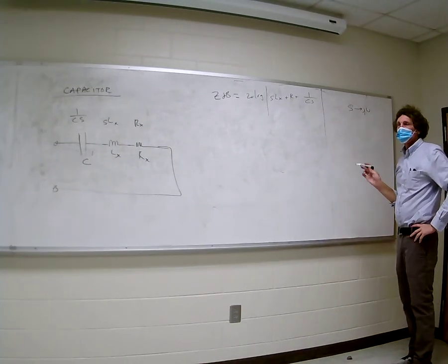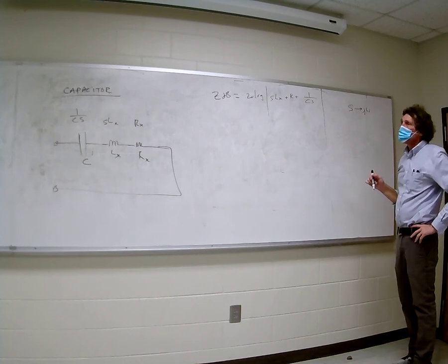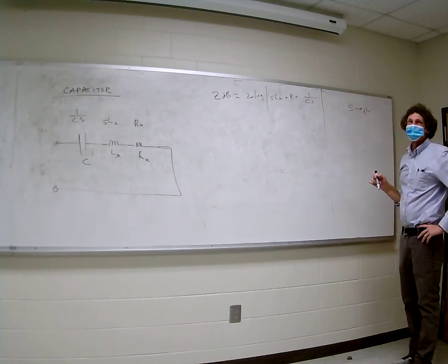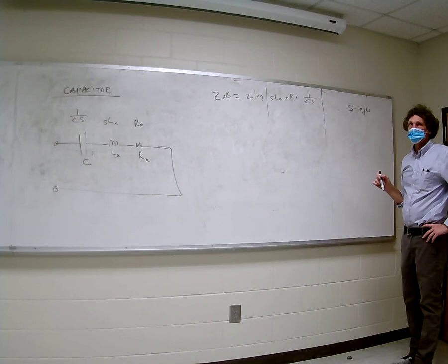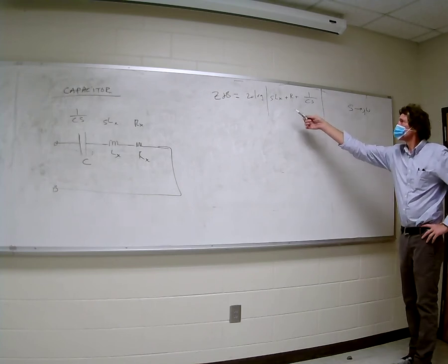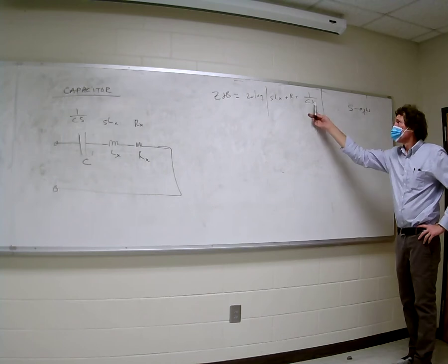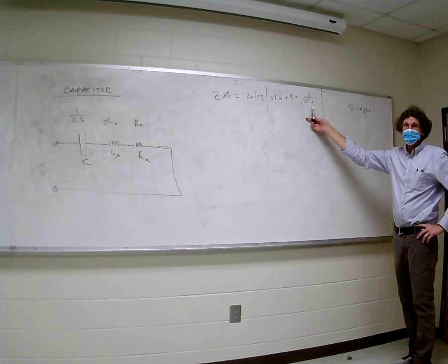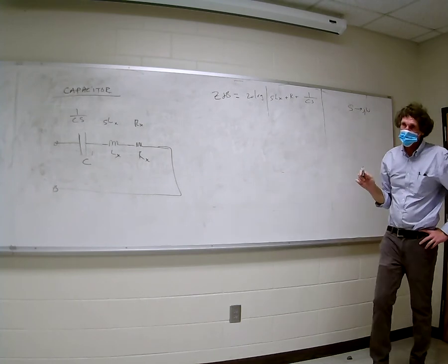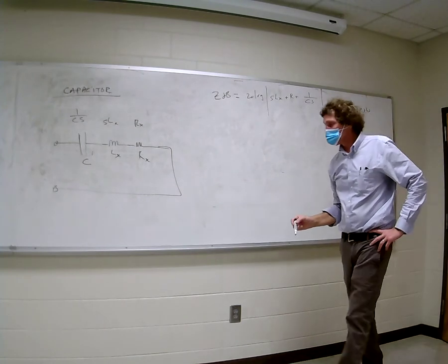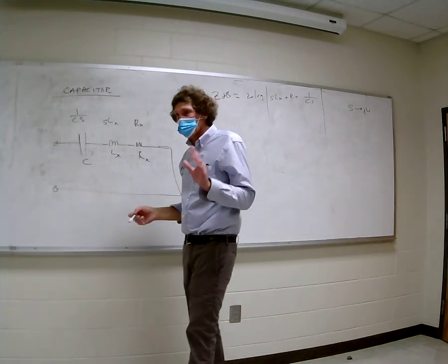And I take one look at this, and I see, well, for a capacitor at 0 frequency, when S goes to 0, what's the value of this? 1 over 0 is infinite, correct, class? It's infinite. An ideal capacitor will always come in from infinity in terms of its impedance. I got to make a comment.